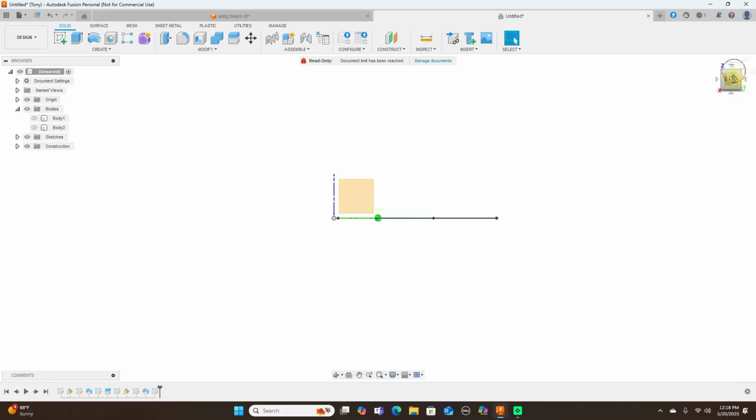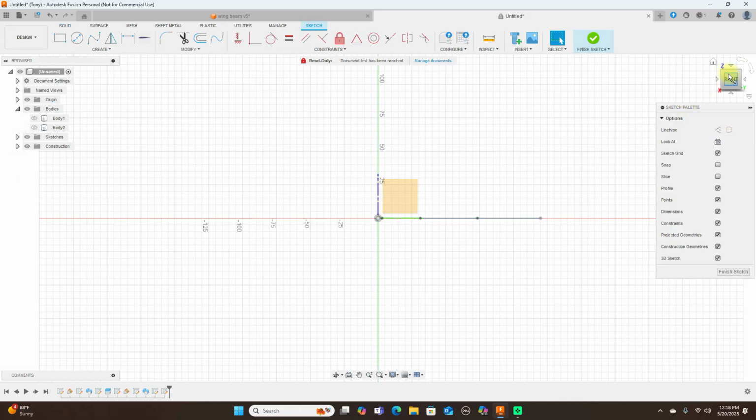And as you can see, it's the same, like with the wing, and then you just create a sketch on this plane here. Now we don't have to put a plane at an angle and use this line because this plane is already on this line. So we create a sketch on this plane here.